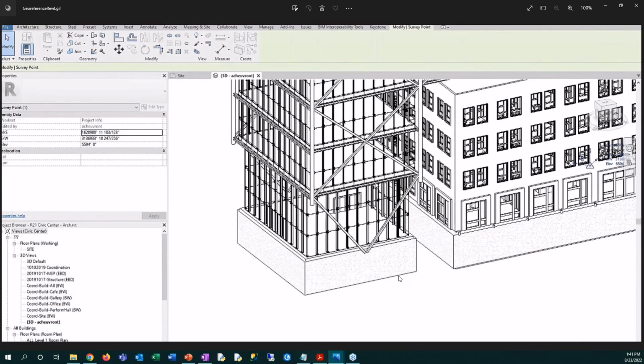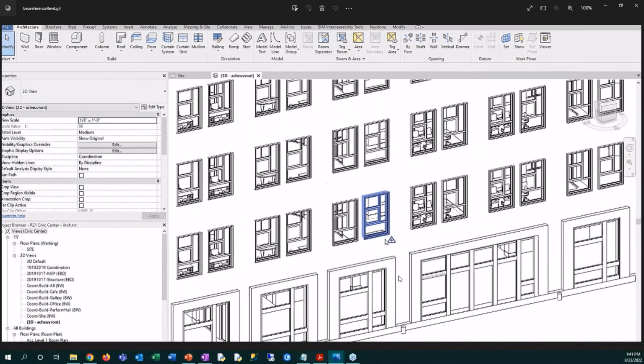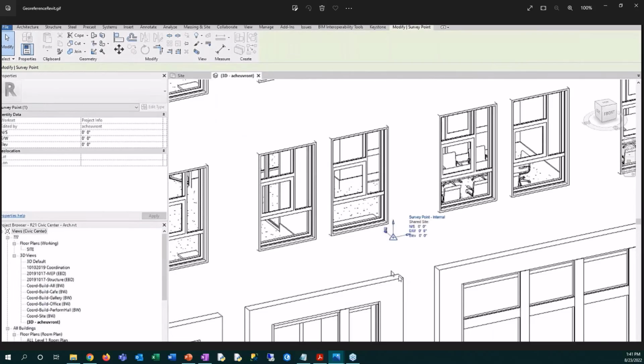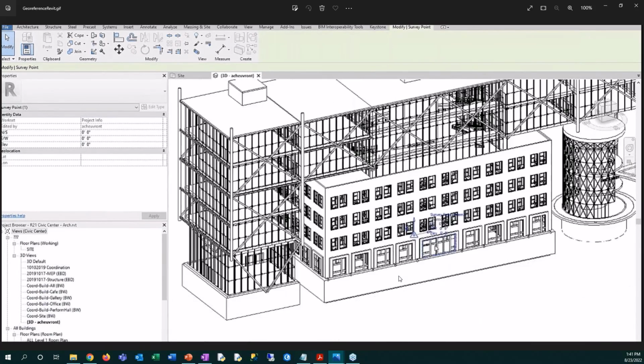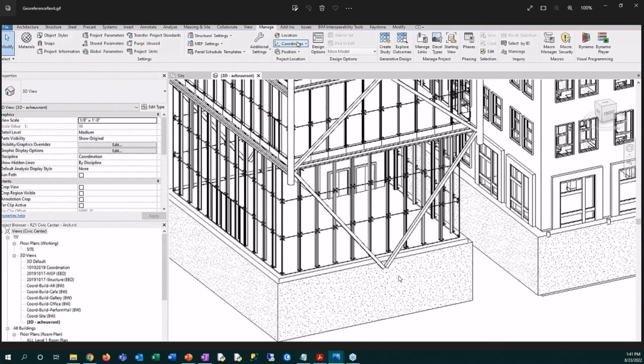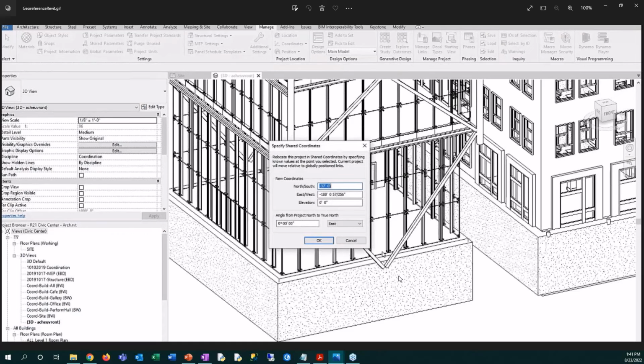And then in doing so, we reclip our survey point to preserve those coordinates. And now when we bring this document into our ArcGIS Pro application, it will be immediately properly georeferenced on the ground, and we might only need to make subtle updates and adjustments using the ArcGIS Pro tools to do so.